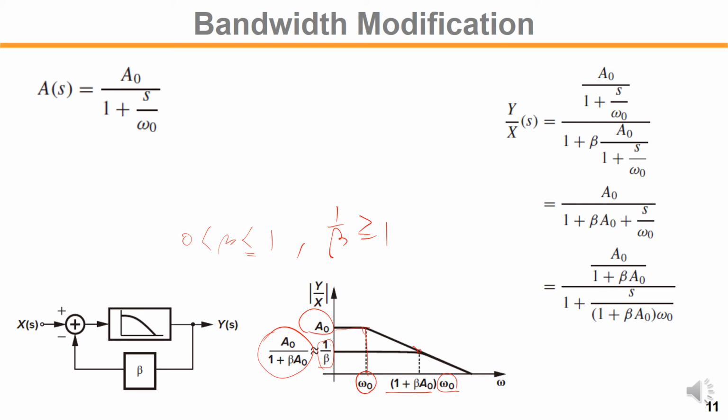As you can see, below this certain point the gain is flat, but after that point it just follows the original amplifier characteristic, meaning within this frequency range, the negative feedback does something. So the negative feedback effect is only valid up to this point. Like that.